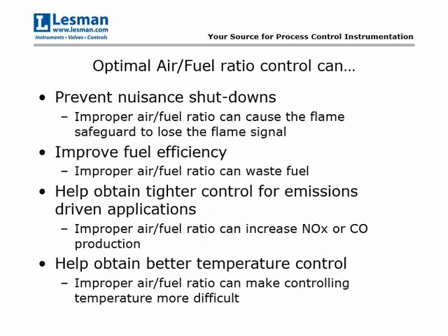Improving the fuel efficiency. A lot of times, the burners we use for these applications are designed to operate at a specific air-fuel ratio because that gives us a good flame signature. When I say flame signature, I'm talking about the diameter and the length of the flame, as well as the discharge velocity out of the burner. If we start burning too rich or too lean, that burner, although it may still be on and functioning, not shutting us down because of a loss in flame, you could be increasing your fuel consumption because you're providing more airflow into the system than what's required for the application. Or if you're too rich and you have a furnace, for example, that requires the higher discharge velocity to stir up the chamber and get temperature uniformity, you'll have a lower discharge velocity running too rich.